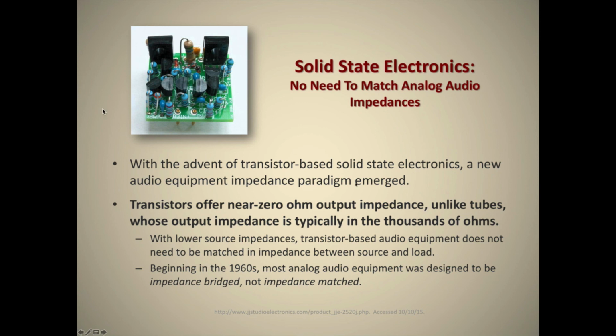And what's cool about op amps, what's cool about transistors, is they offer almost 0 ohm output impedance. Very, very low output impedance. And this is a stark transition from tubes that offered a very high output impedance, which means you don't need a giant transformer on the output of this thing. You could put one on there if you want, but you don't need it.